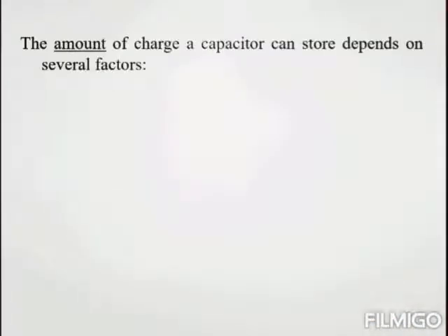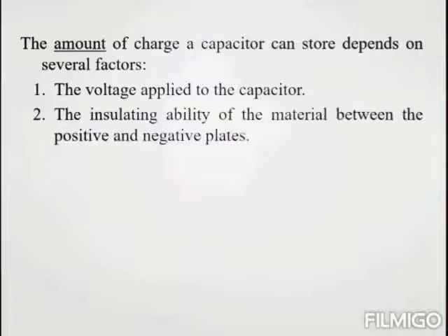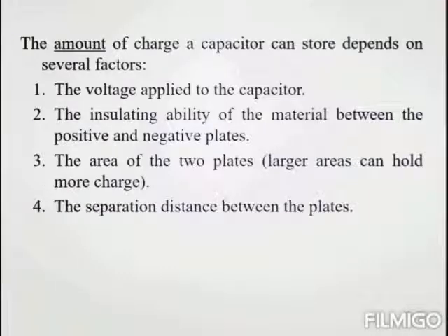The amount of charge a capacitor can store depends on several factors. First one, the voltage applied to the capacitor. Second one, the insulating ability of the material between the positive and negative plates. Third one, the area of the two plates. Fourth one, the separation distance between the plates.